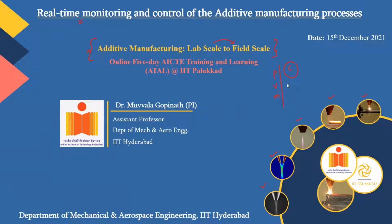Typically, in most cases, people say that they will control laser power to control the heat input, but that is not the only parameter you need to control. Sometimes the standoff distance plays a major role. There is no need to touch these two; just by touching SOD, you can rectify a lot of errors that occur in additive manufacturing.